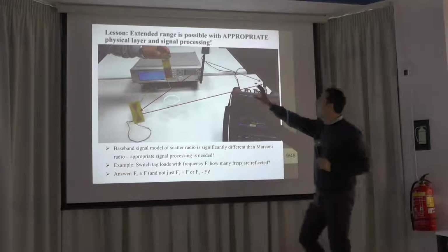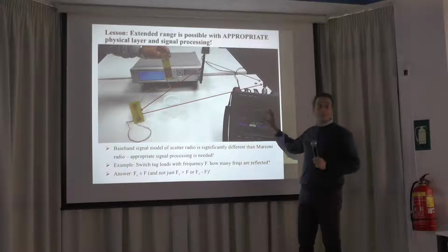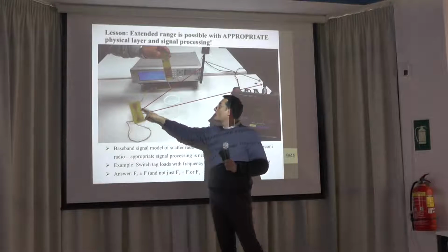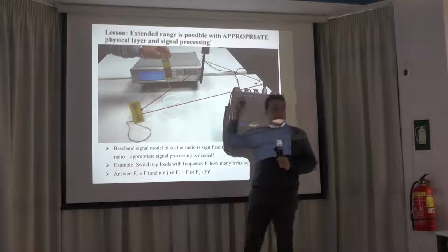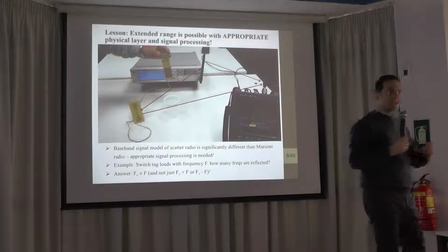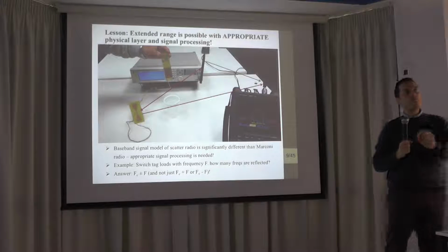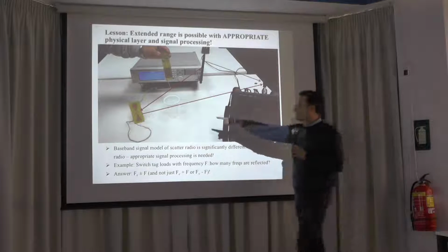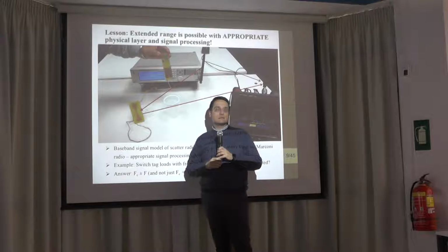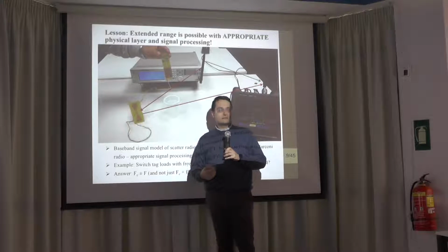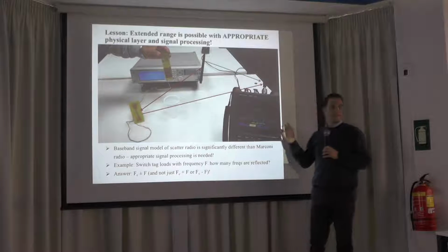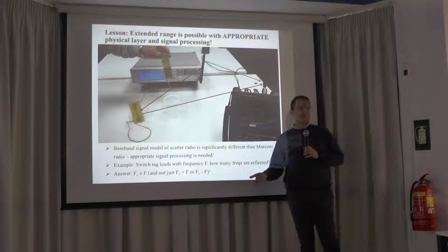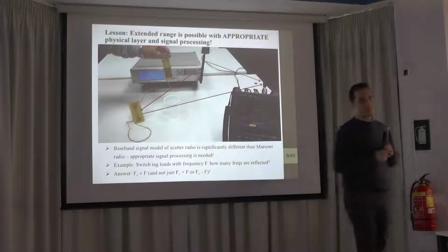And here, you can see all the basic ingredients. You have the illuminator, you have the receiver of the backscatter information, and you have the antenna connected to my sensor that basically reflects the impinged signal, changing its characteristics depending on what I want to measure. Okay? What is the advantage of this technology? You can build extremely low power wireless sensors. Provided, of course, you are smart enough to replace this 6K machine with a $10 machine connected to your computer and intelligent signal processing. Okay?